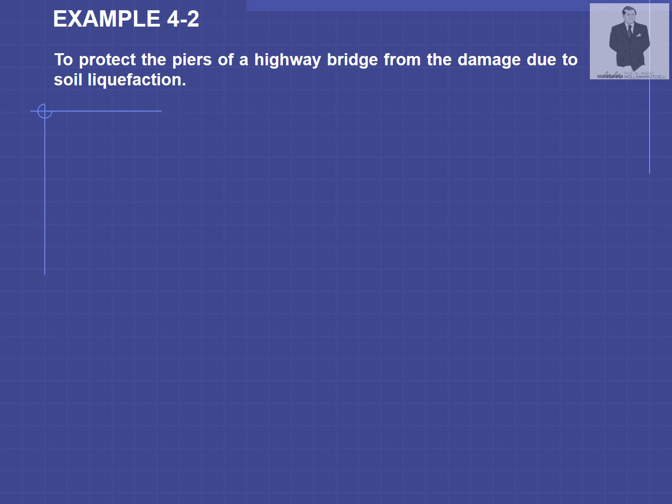When the excess pore pressure equals the total stress of soil, effective stress becomes zero. That is to say, the shear strength of soil is lost, thus the bearing capacity. So the structures over these soils will collapse. They may undergo tilting, overturning, or sinking into the ground.